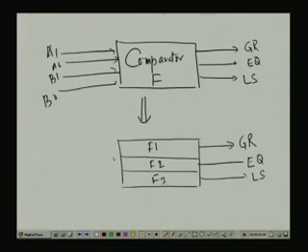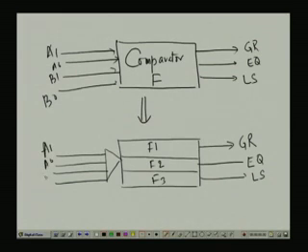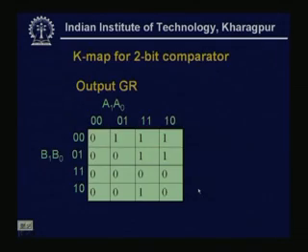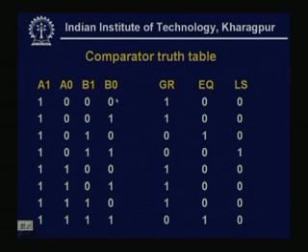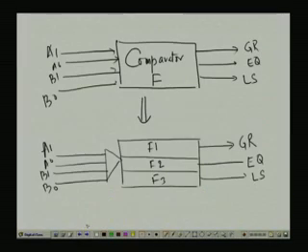Say all inputs are fed to all the modules. This is the situation, and now this F1, F2, F3 we have to design. So, what we can do now is partition this into 3 sub problems. Actually, there are 4 inputs and 3 outputs, so we are partitioning it as F1 with 4 inputs and 1 output, F2 with 4 inputs and 1 output, and F3 the same.